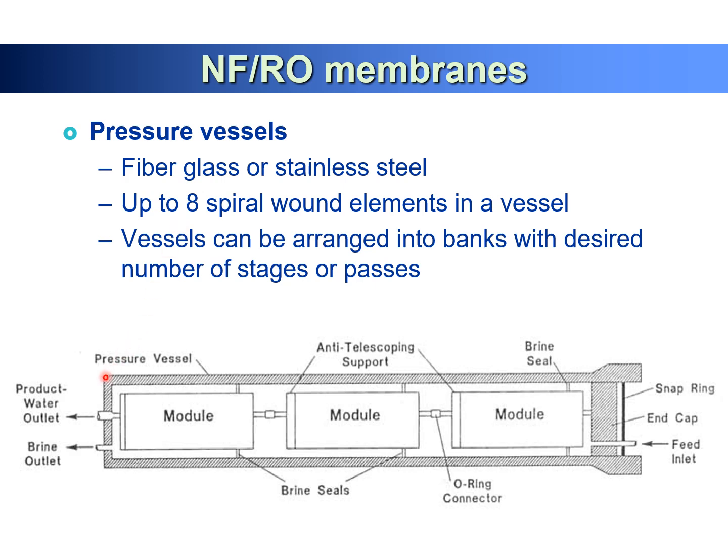If you look at this diagram, the outside is the pressure vessel. Inside the pressure vessel, each element will be located here. Your feed water passes through, and your seawater flows through this channel. Then you have permeate water flux that can be collected from this product water outlet, and this is the concentrate, and then brine comes out from this pressure vessel.